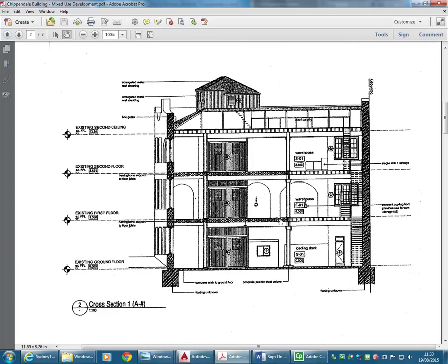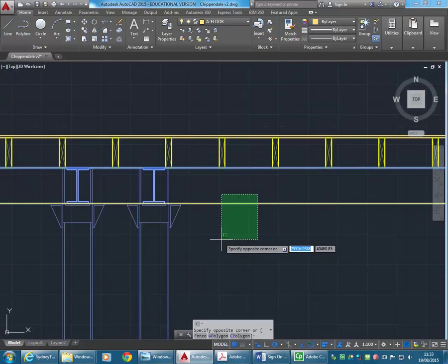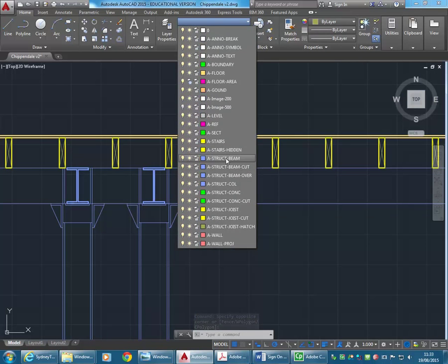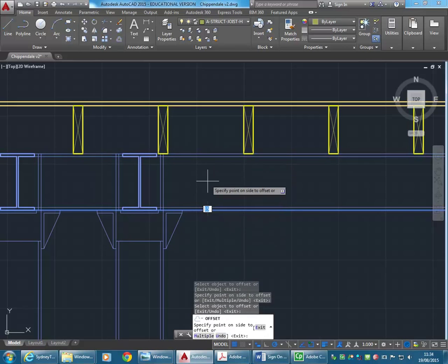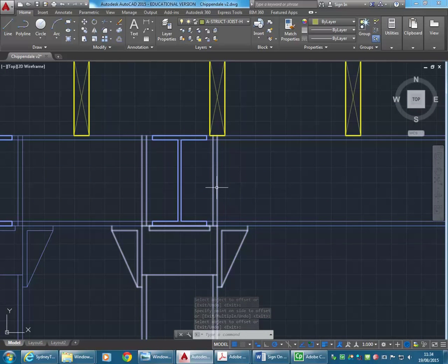Again, hand drawing. I just drew whatever. But would you not really see it? Oh, no, so there's a beam there though. So you will see the line there because of the top of the beam. So you will see it actually. So that really is now... So that should make it clear. And then the joists are heavy, so they read as being cut, which is nice. And you could just offset 15 mil above and below those lines. And if you really want to be fussy, trim in between your columns.